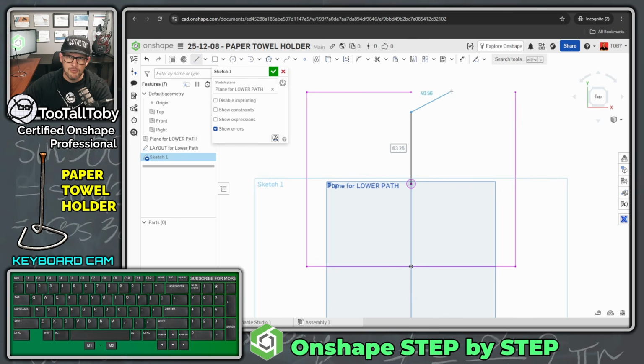We can move away. We just like click and then move your mouse away, and then put your mouse over that endpoint and then move away again, and that'll take you into a tangent arc command. So then we can single click again. We can move away from that one. If you move at just the right angle, you can pick up tangency as you're moving away here with the line. So then you can single click, you can move away, put your mouse over the endpoint, come back, touch the endpoint, move away again. That puts you into a tangent arc. It's kind of nice.